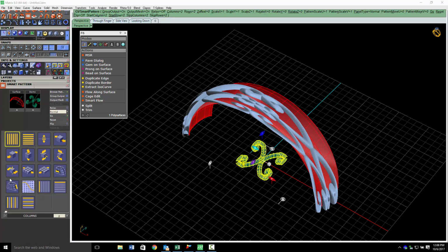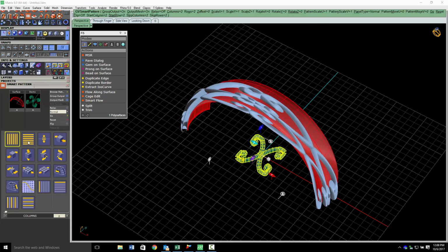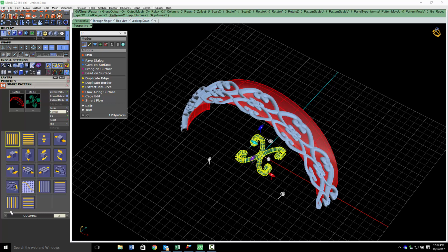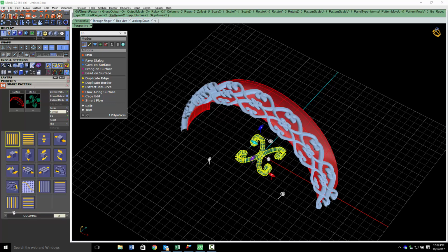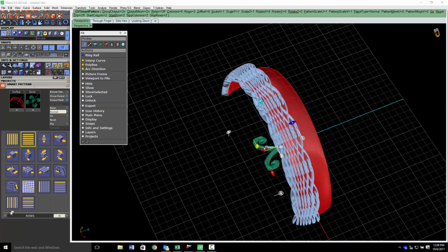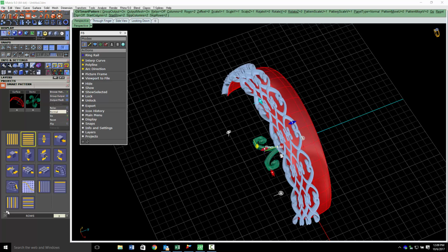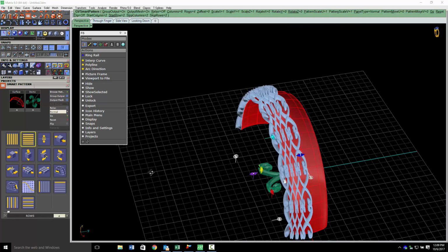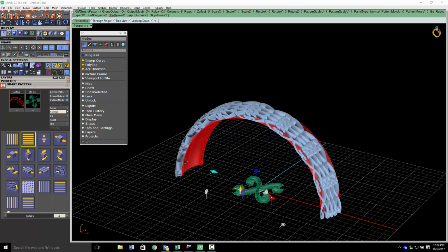Over here, we've got the ability to start to add columns, add rows. And so I'm going to stick with a couple of columns here from this particular part. And what the columns are is how far out do you want this pattern or this texture to go. In fact, let's just add a few more just like that. And then rows is going to be how tight are they. Okay, so if you want, let's go 5 rows, 4 rows, whatever it might be.